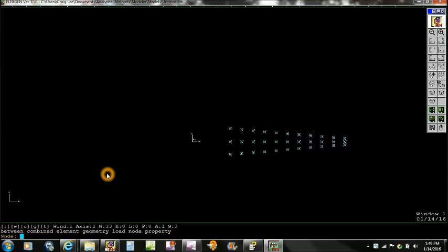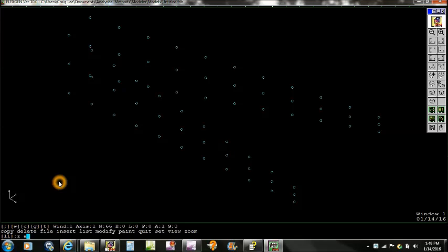Now we want to copy those and start to rotate about the z-axis here. So we're going to do iteration 1 to begin with, and we'll do rotation RZ of 20 degrees. And yes, you can't see them very well, but we'll change the view direction here. And there they are. So we started out with this one, and we just created that one.